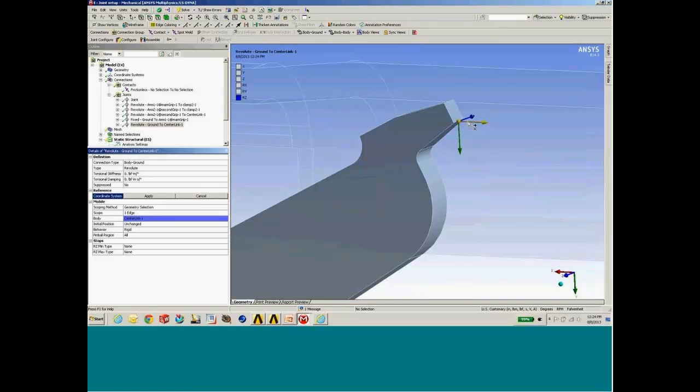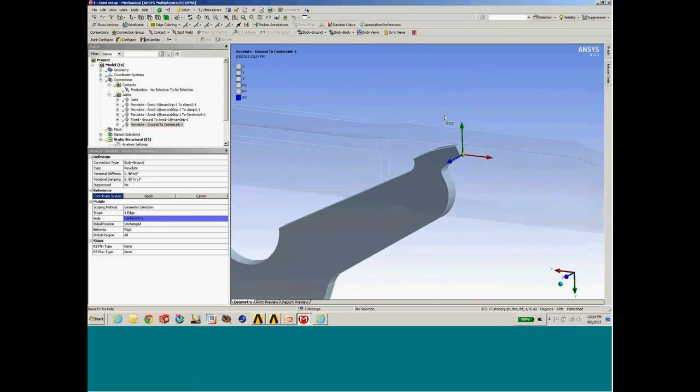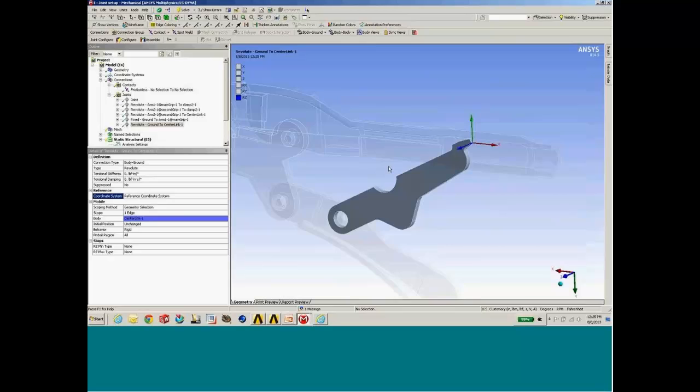You simply pick on the particular axis that you want to move and pick on the position that you'd like to move it towards. So it's just as simple as that. So pick on one and rotate it over if you have to. So our local Z is the blue axis. That's going to be the axis about which we're rotating. We've got that particular joint set up there.